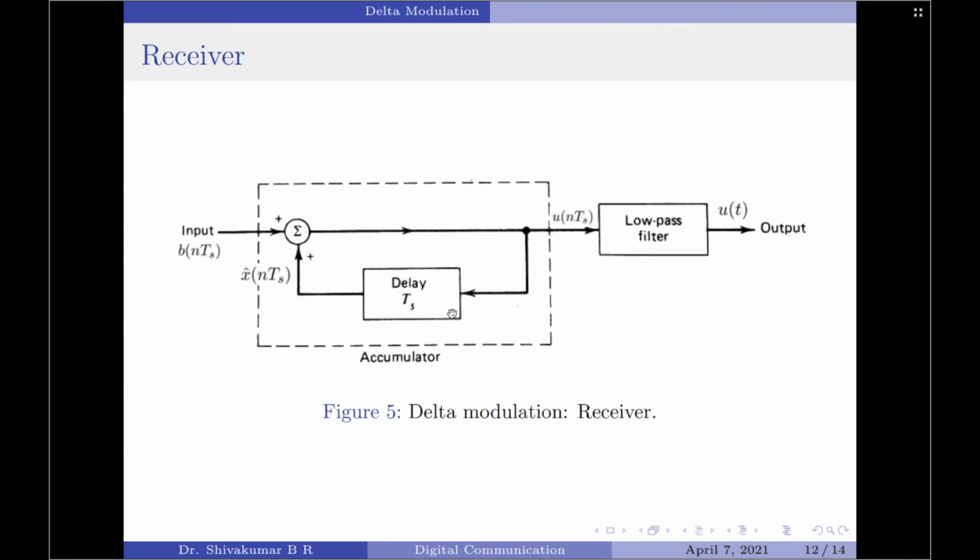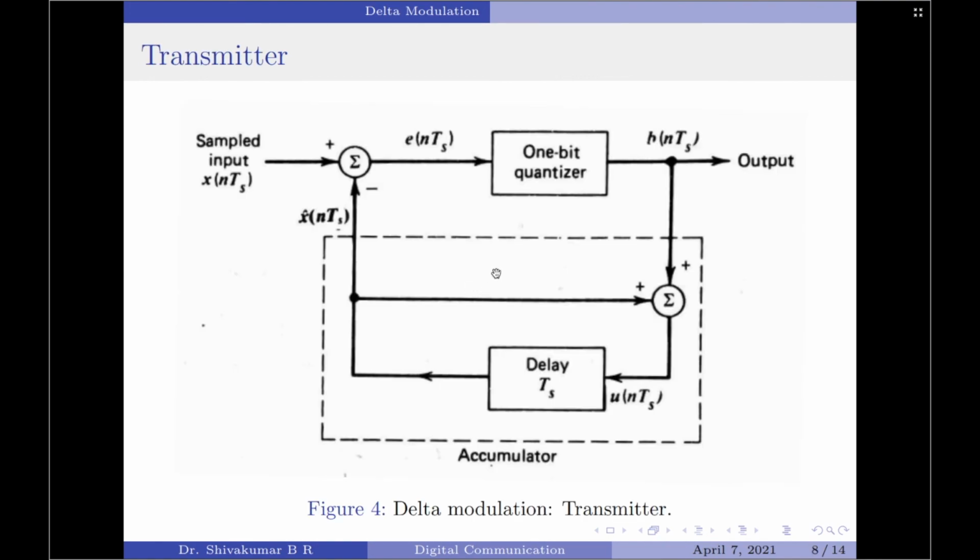By comparing the differential pulse code modulation and the delta modulation receiver diagrams, we will see that except for an output low pass filter, delta modulation in fact can be considered as a special case of differential pulse code modulation. You should note, delta modulation particularly offers two unique features compared to DPCM. The first one is the use of a 1-bit code word for the output.